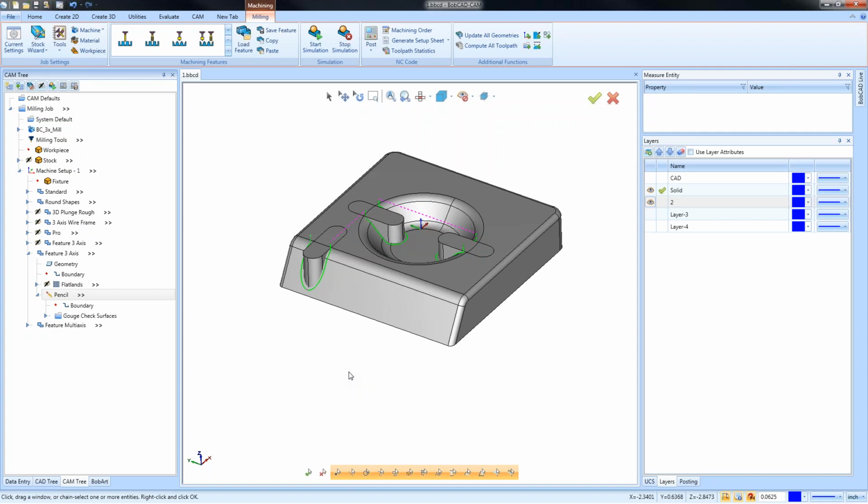Okay, now again, it's really important, guys. This job tree here, I prepped these so that I could demonstrate specific topics, but you should be using the job tree templates. And really with just a little bit of work, a little bit of testing, you can set up a standard job tree template that could be applied to a whole product line or a whole process and spend less time figuring out the details of the settings for the toolpath and spend more time just selecting the geometry you want to cut.